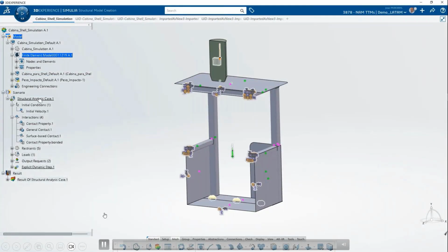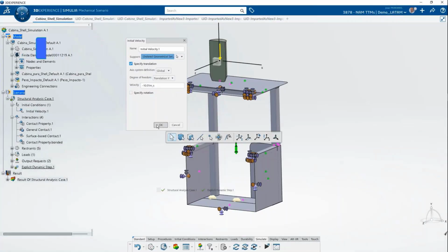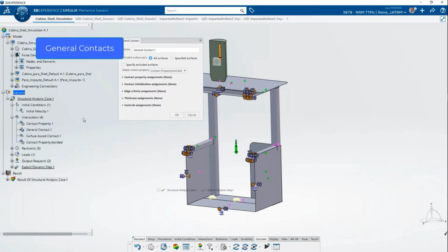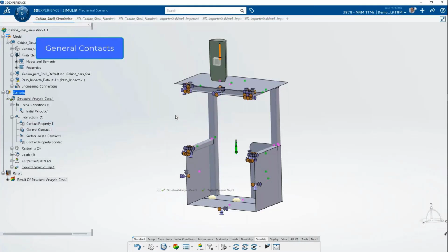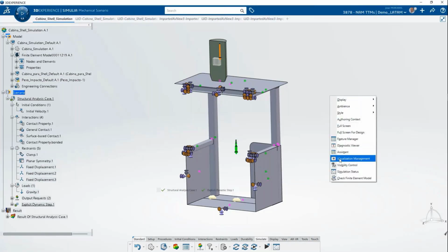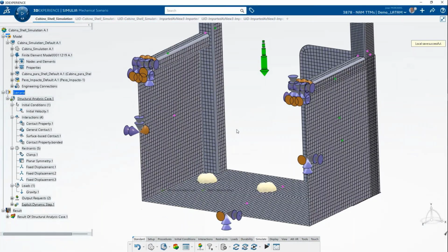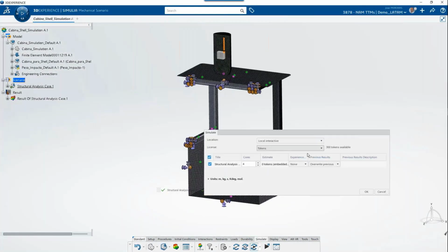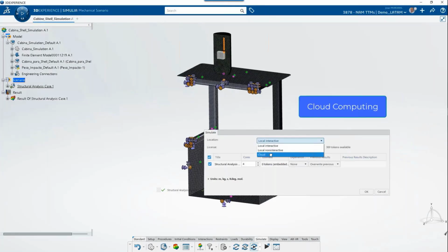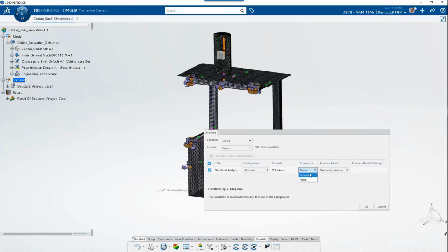Again, the working environment to do this type of analysis is very simple. We have created the same geometry here. Since the geometry is symmetric in nature, we have taken half of it, and we are quickly setting up the analysis where we have created the geometry, defined the symmetric boundary condition, and defined a very special type of analysis called explicit dynamic, for which Abaqus is very well known as an explicit solver. We have meshed it. You can see how beautiful the mesh looks on this particular geometry. Once this is done, we can quickly run the analysis either locally or, of course, on the cloud, which would be the best option for this type of analysis.